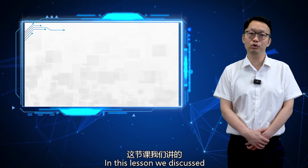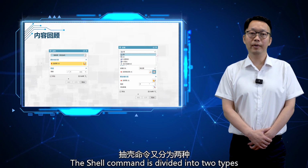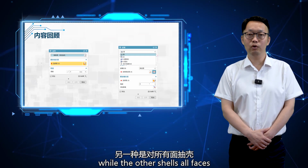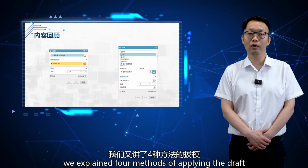In this lesson, we discussed the shell command and the draft command. The shell command is divided into 2 tabs. One removes a face and then shells, while the other shells all faces. For the draft command, we explained 4 methods of applying the draft.